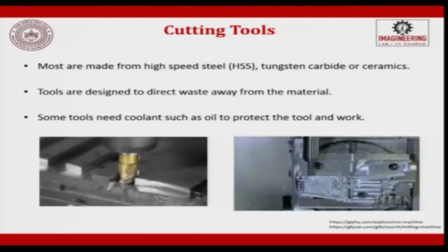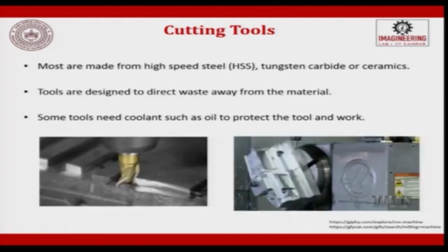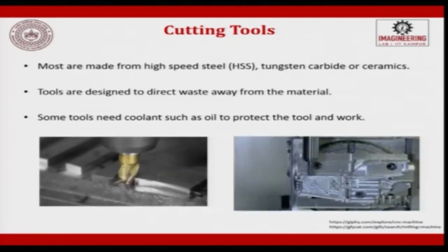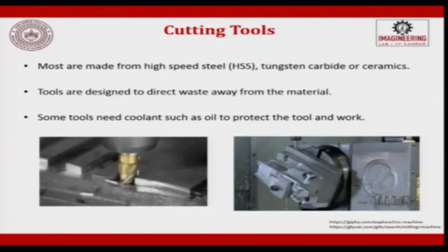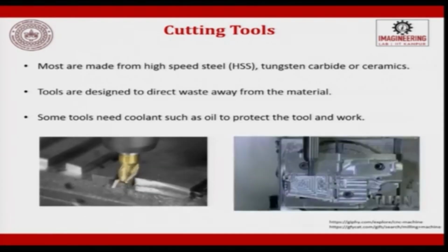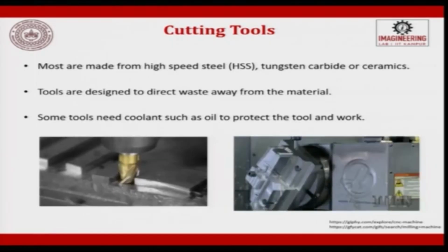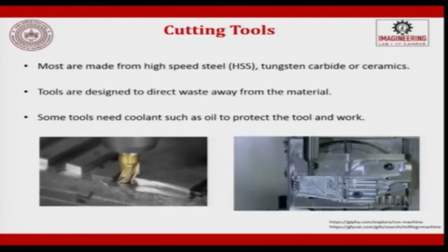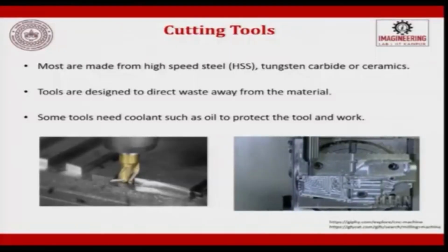When we talk about cutting tools, as I told you earlier also, cutting tools are different from machine tools. We have never talked about the cutting tools. The cutting tools are harder than the workpiece and they have a geometry which gets superimposed on the workpiece to generate a profile. It also has a relative motion. So, the features are generated because of the superimposition and the feed movement, or the relative movement of the tool with respect to the workpiece, and you get the desired output.